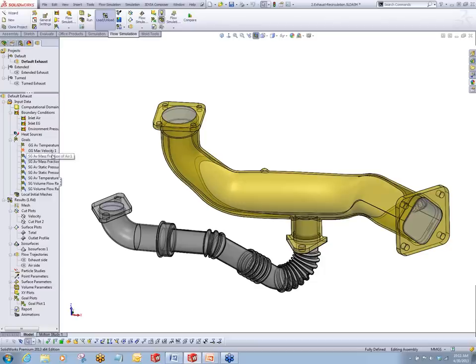With Flow Simulation, we can set up goals that allow us to get quality results for various parameters. The parameters of interest for this project would be the pressure drop in the pipes, the exit volume flow rate, velocity, and most importantly, the outlet mixing efficiency. These goals allow us to get the quality results that we're looking for, which can be post-processed in very nice ways once we've gotten results.